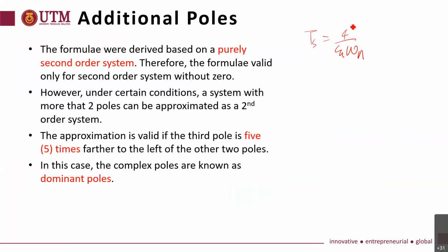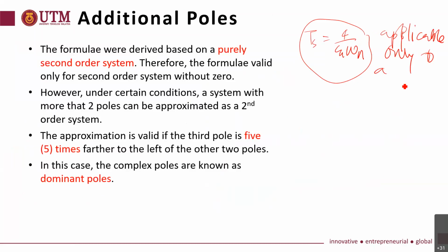This formula is applicable only to a purely second order system. All the formulas, overshoot, Tr, Ts, Tp, are only applicable to a purely second order system.